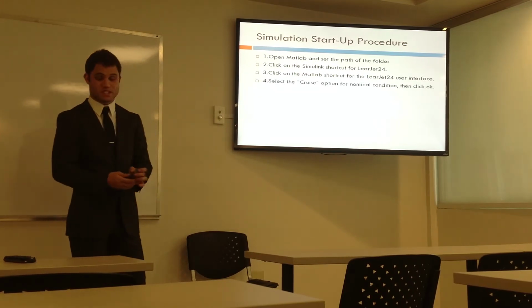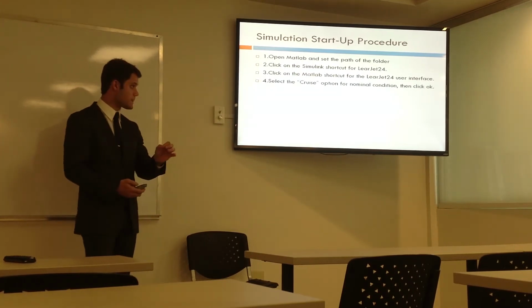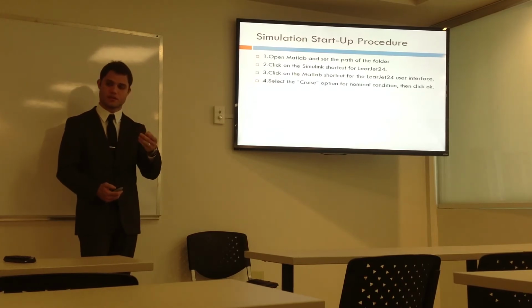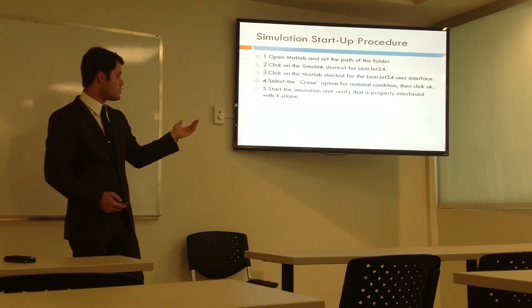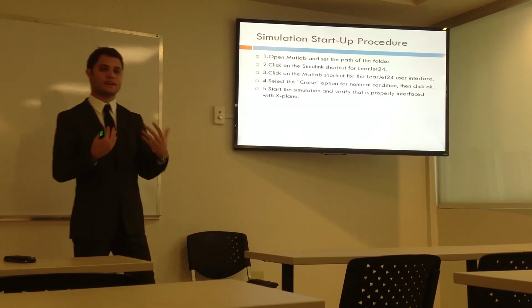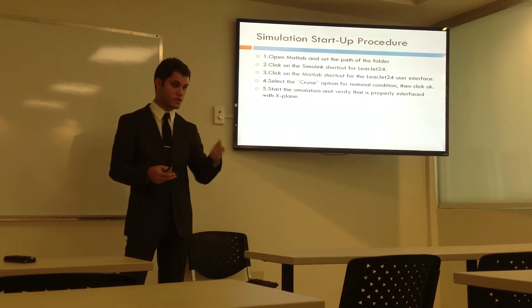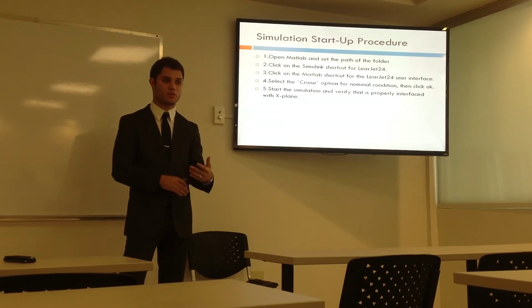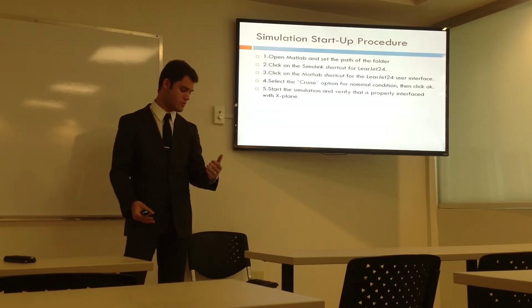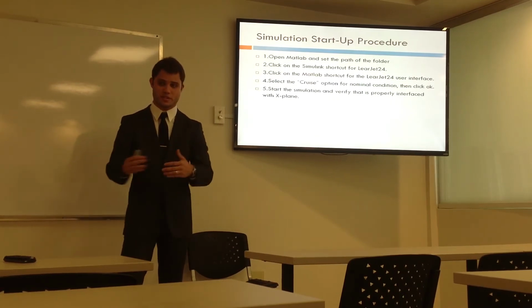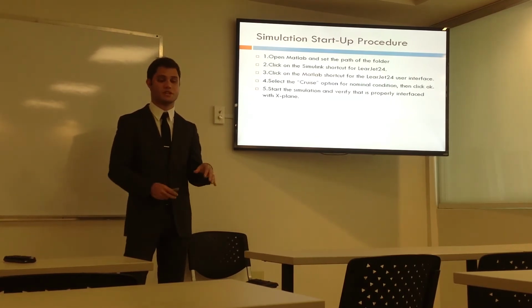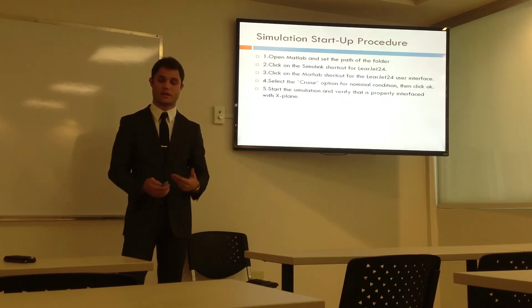Once you have that, you're going to select cruise on for the flight conditions. That way all parameters are within the known range. And you're going to start the simulation and verify that they're synchronized, that the control inputs that you're giving are the ones that the aircraft is reacting to. Because if you're moving the joystick forward and backward and what's reacting is the throttle, we need to make sure we readjust the input channels before we continue with the flight test so we can get the correct data.